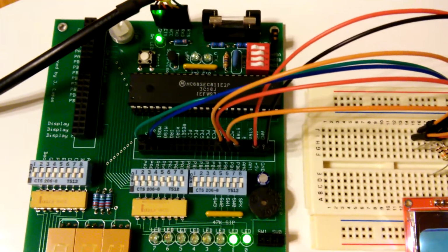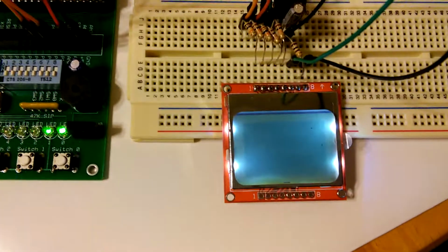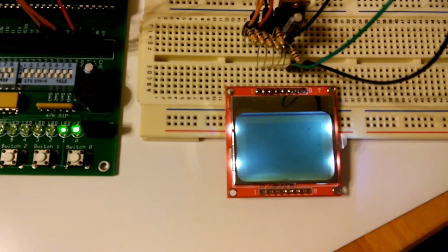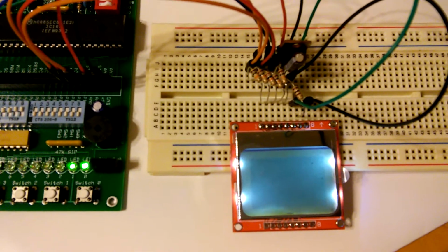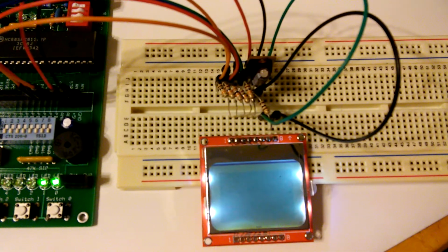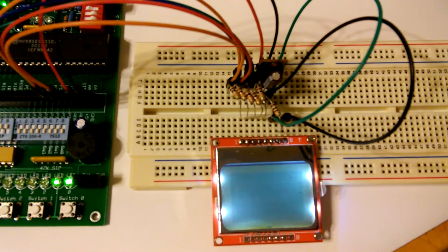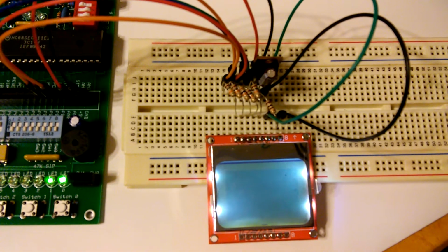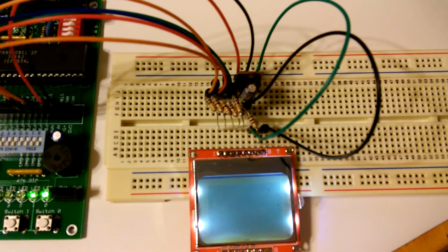Now, the 68HC11 operates on 5-volt logic, while the LCD module operates on 3.3 volt logic. So some signal level translation, or conversion, had to be done, and this is done via the 10K ohm resistors seen right here. By putting a 10K ohm resistor in series with the 5-volt signal, it would drop it to about 3.3 volts. The 3.3 volts VCC is provided by a 3.3 volt voltage regulator.